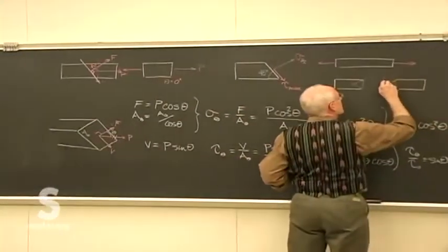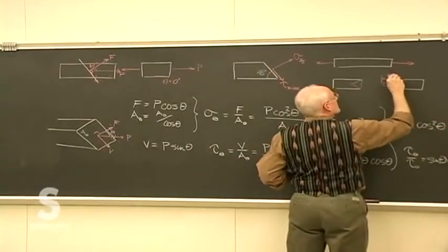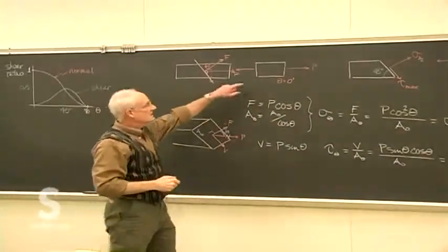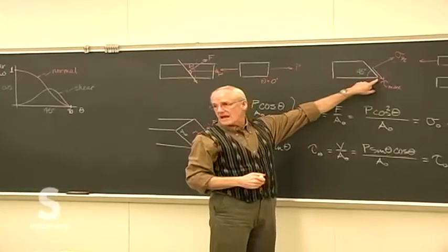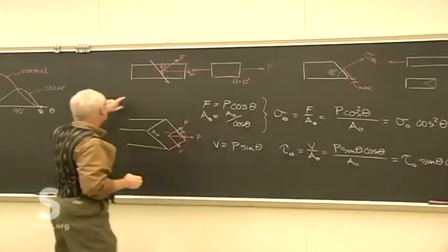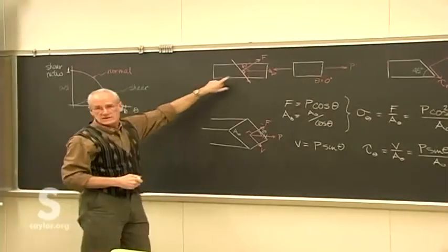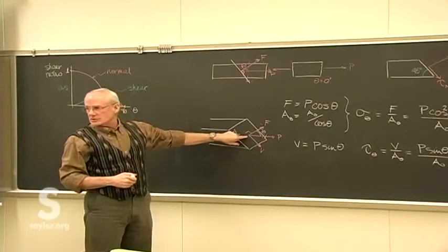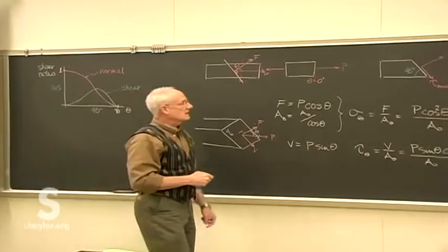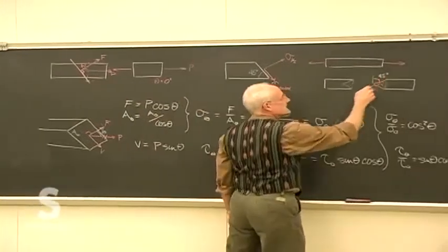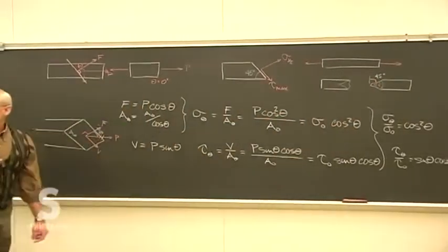But this is at approximately 45 degrees because of the material's inability to withstand the maximum shear at that oblique angle. Remember, our look at all of this was at an imaginary angle. We determined that the maximum shear response was at an oblique angle of about 45 degrees, and that's indeed where the material tends to fail.